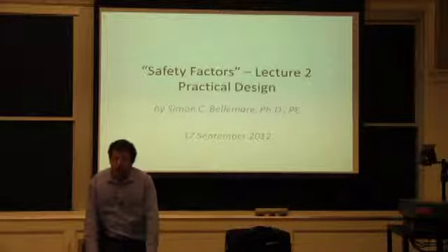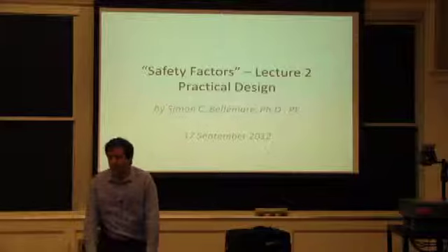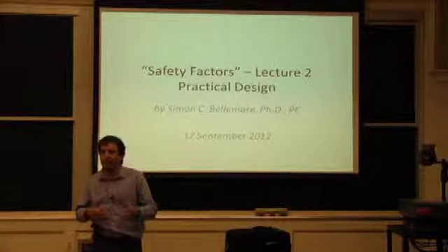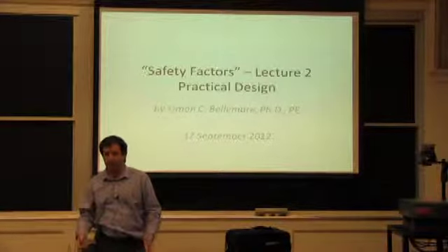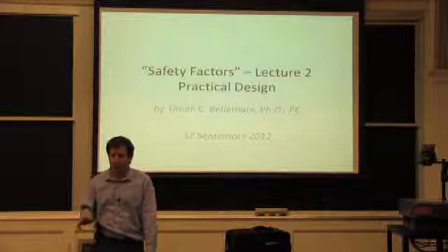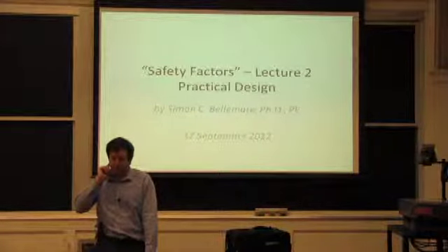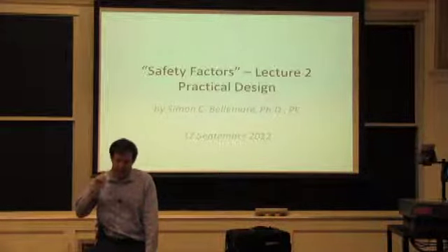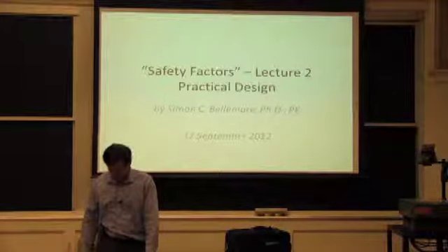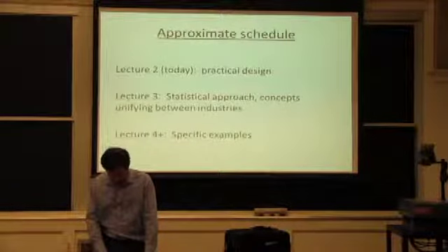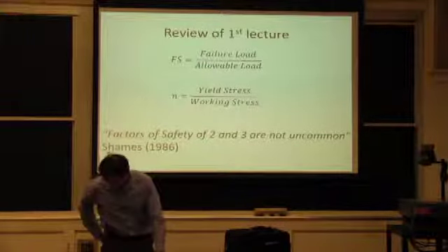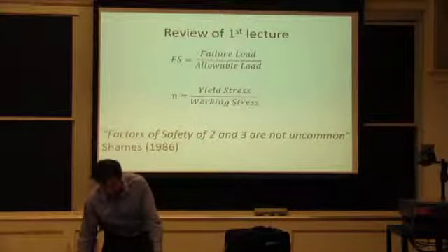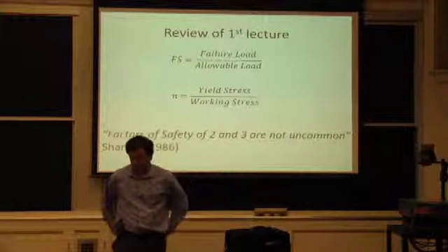One of the reasons I'm doing this in the context of factor of safety is to show that depending on how conservative you are in determining the demand, your result will be different. As far as you won't need as much of a safety factor. So the safety factor that we talked about was the failure load over the allowable load.